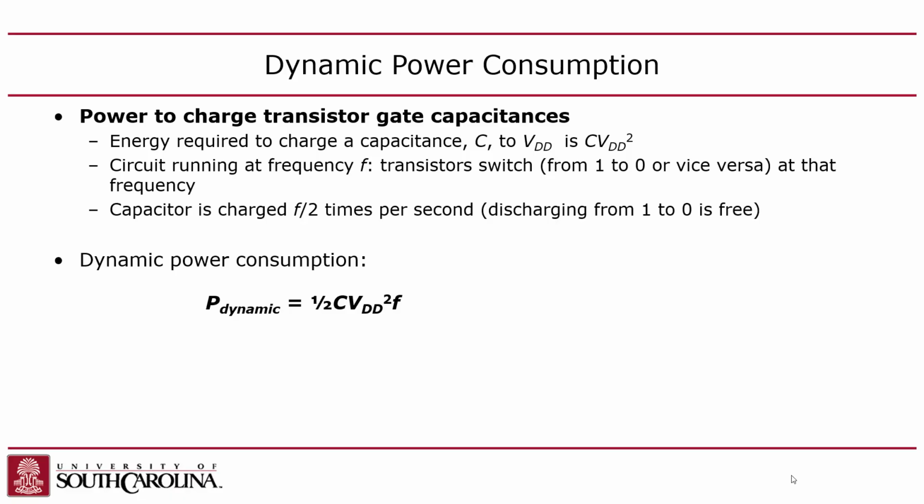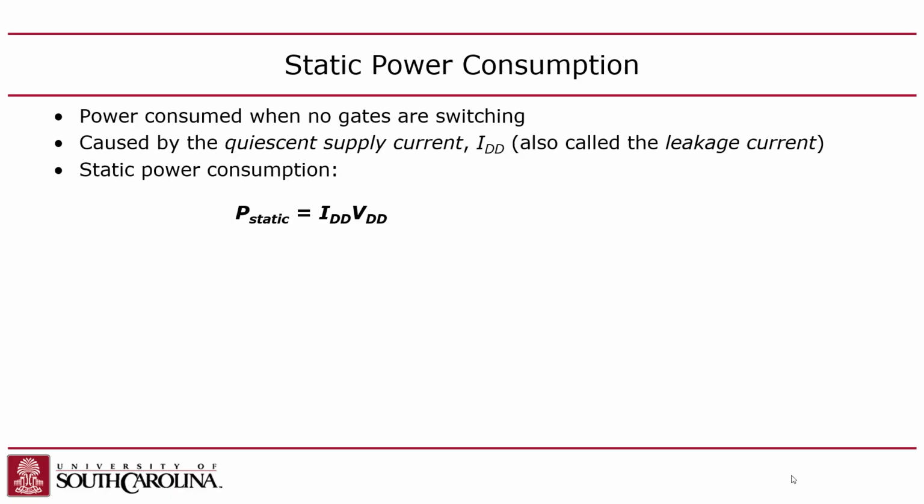I could create more powerful processors, powerful in the sense of computational performance, without spending any more power. That almost seemed too good to be true. Well, it was, because Dennard scaling ended about 10 years ago. That's no longer the case. The technology has changed, and the savings in capacitance are now being outdriven by the increase in transistors. That's just the physics of the semiconductor. So there's no more Dennard scaling, there's no more free lunch.